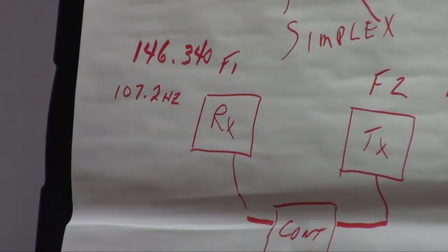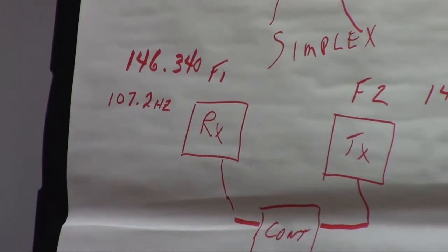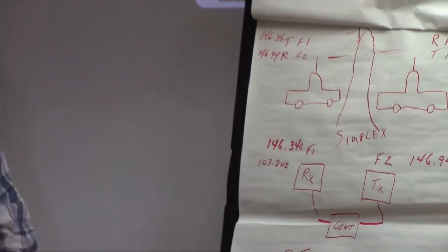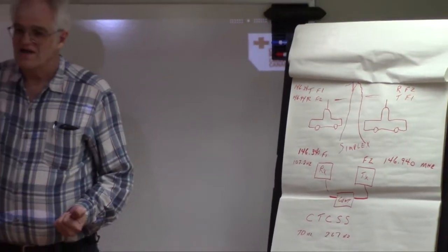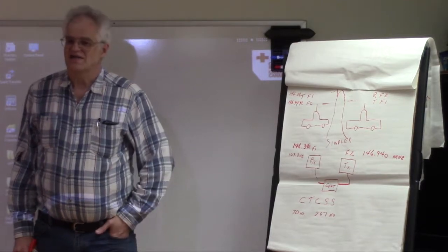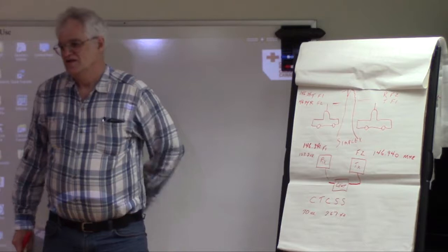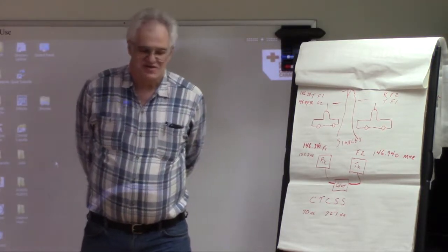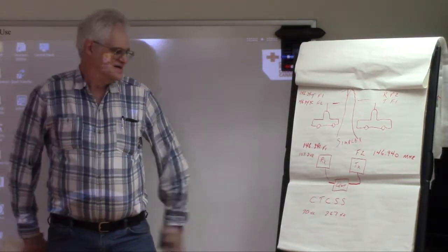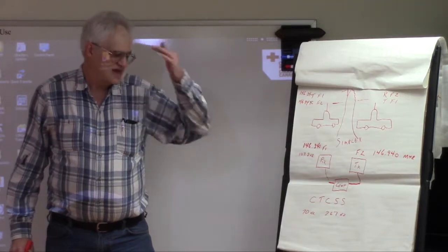which is a feature built into most radios, and that's typically called tone and code. That's the actual technical term for it. You'll also hear it referred to as PL tone, which is Motorola's patented name, it was called Private Line, which does the same thing. General Electric had their patented name, Channel Guard, for the same thing. They all mean the same thing.